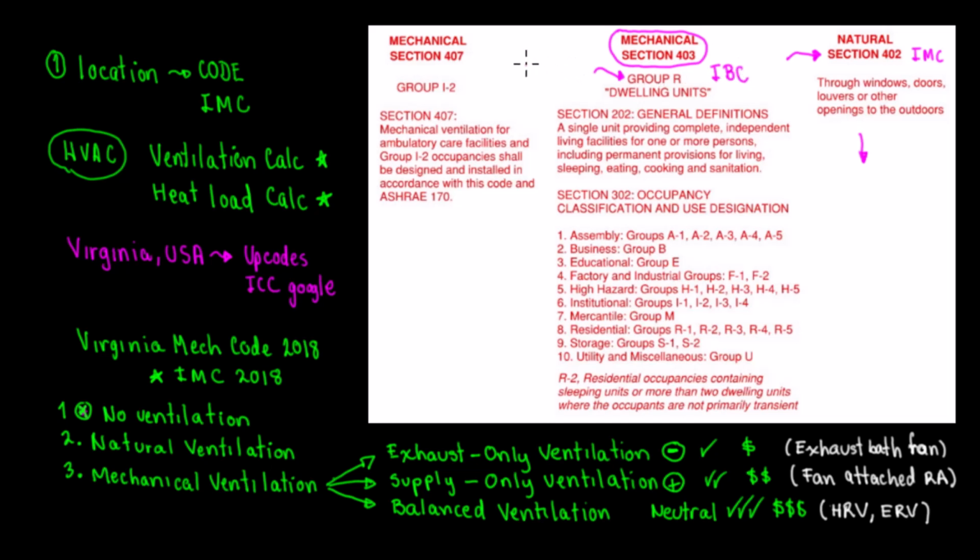They're going to give you the drawings with dwelling unit number 1, dwelling unit number 2, dwelling unit number 3. They will already have this classification based on the International Building Code. In the drawing, it is going to say, for example, R2 in here, and in here S1, depending on the occupancy classification.